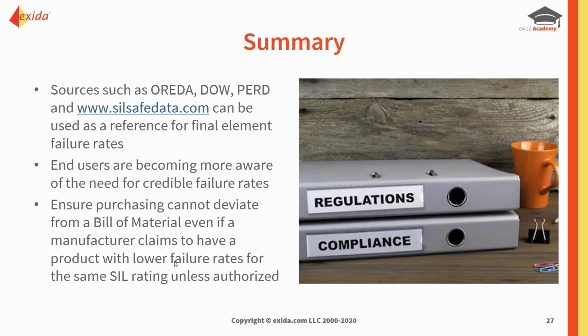If they're the same SIL rating, then it should be okay, but we'd still need to do a verification from the SIF point of view. Then he said, after a little while, okay, so what if they're not certified? And I said, well, then all bets are off because we have to do a prior use justification. And I said, so what happened?